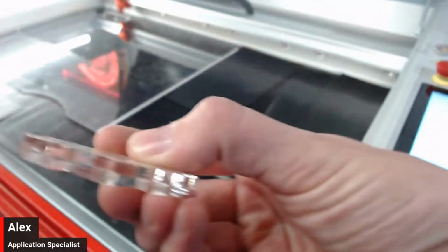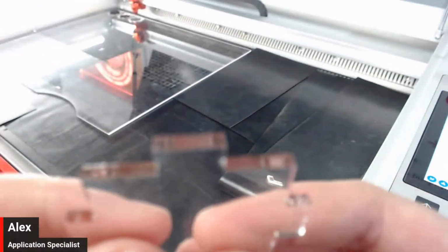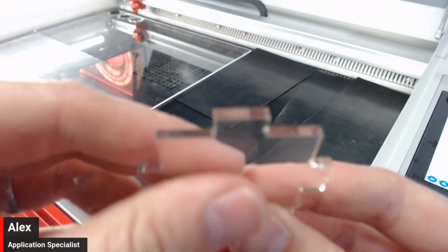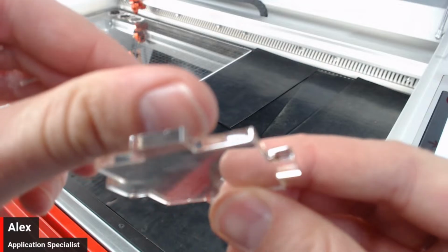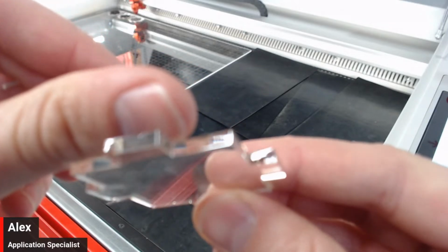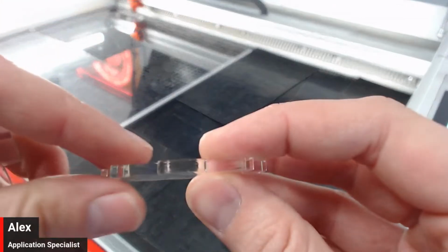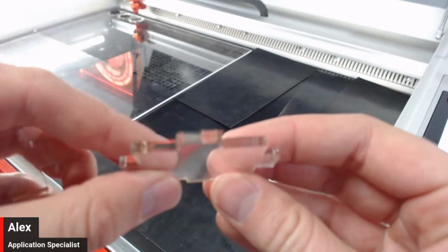Here we go. So the very first cut we did was a lot slower, and as a result, let me see if we get it to pick up. It has then obviously clear. Doesn't give the best example, but you can see hopefully we have a pretty much perfectly smooth flame polished edge here. Yeah. So that is just achieved by making sure that we're putting in enough heat.